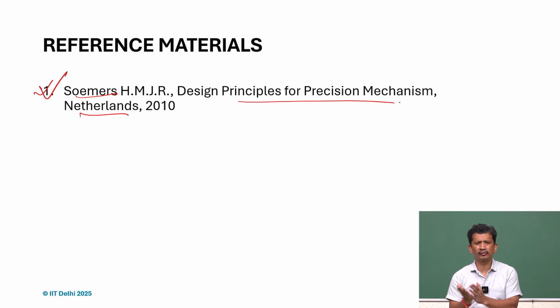For those kinds of applications, we may need very high stiffness values. But on the other hand, if it's a very sensitive equipment, or we want to support something and not transfer any vibration or noise from the ground, then it has to be supported with very low stiffness values.